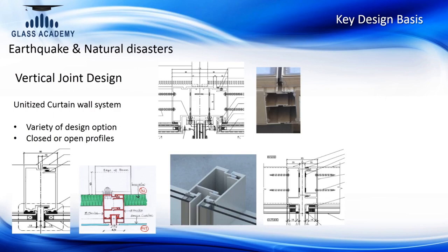Facade systems have no definite rule for using a particular standard profile, unlike steel design. In steel design we have standard profiles like an I-beam, C-channel section, angle section or a hollow section. But for curtain wall, the engineer should be familiar with what is available, what is possible, and what the limitations are here. And you can see the profiles which are supporting the facade system have no definite shape. It could be many different shapes here.